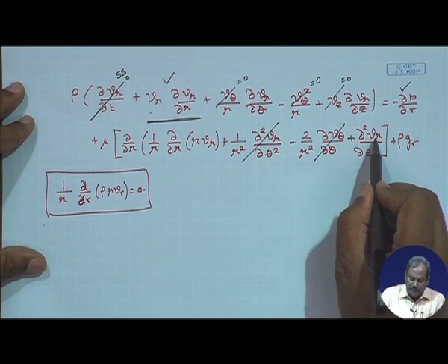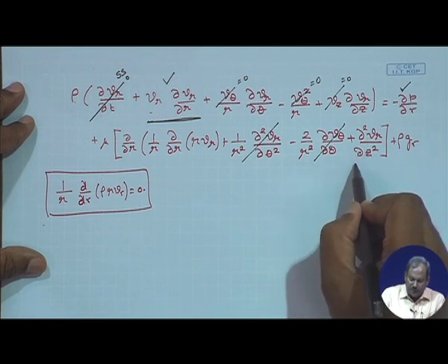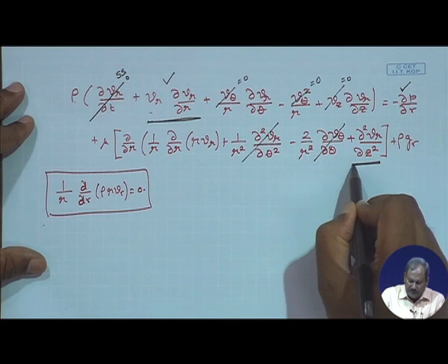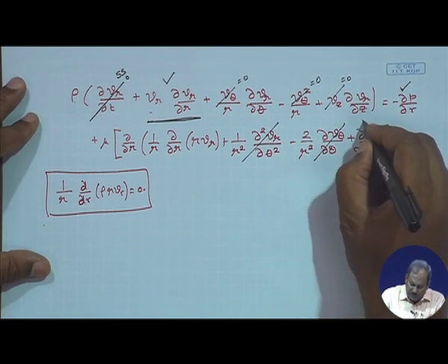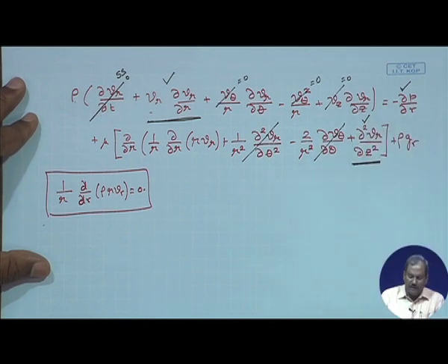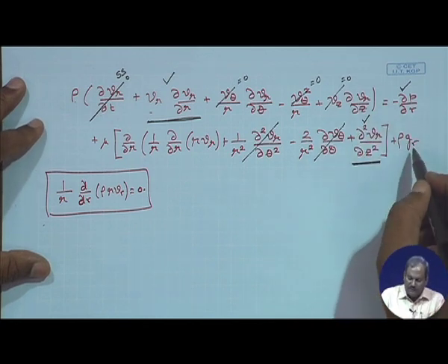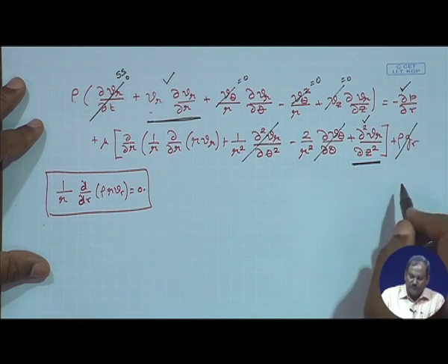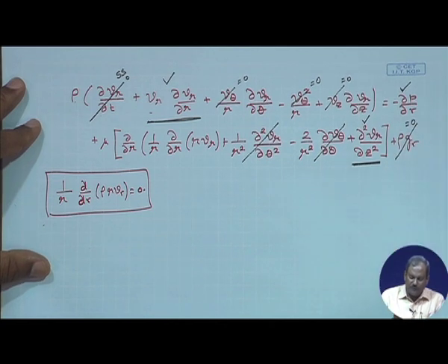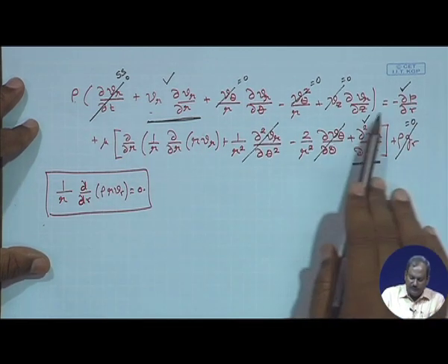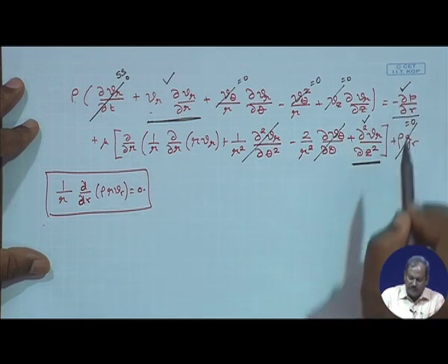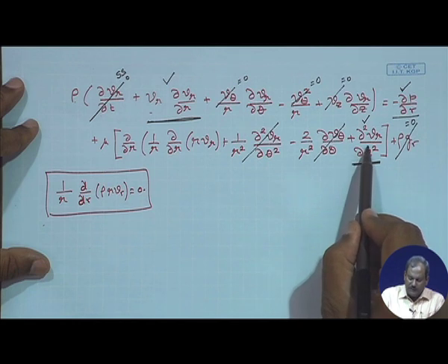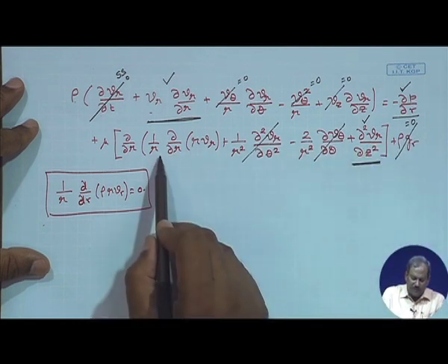However, del square Vr is a function of z. So, I cannot neglect this term, I cannot equate this term to 0. So, this will also remain in the governing equation. And since the disks are horizontal, there is no body force acting on it. So, therefore, this will also be 0. So, of all the terms on the right hand side, this is non-zero, which will remain in the governing equation. This is non-zero, everything else is 0, and now we come back to this term.